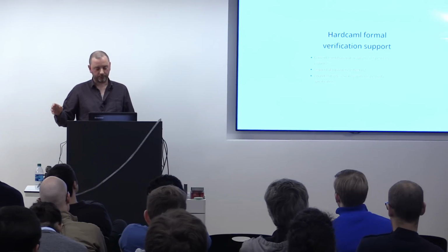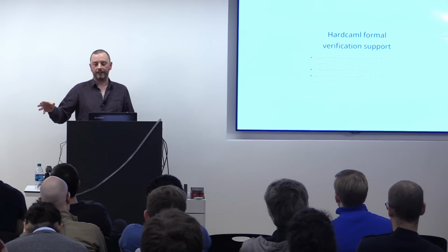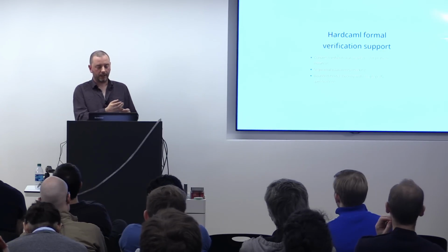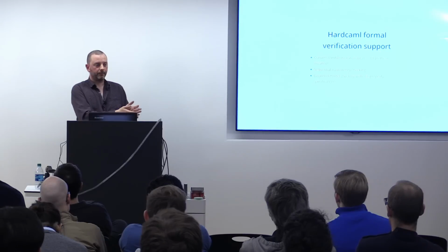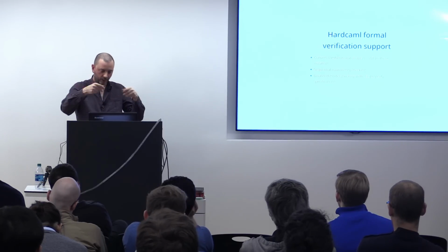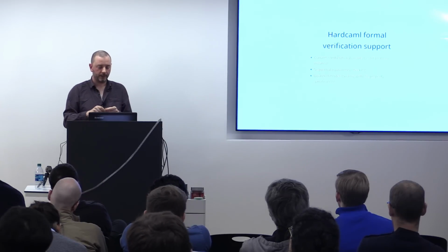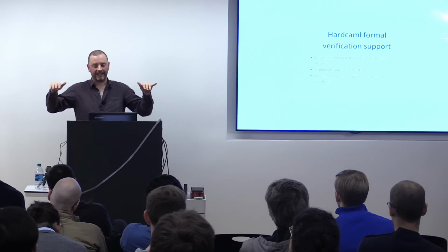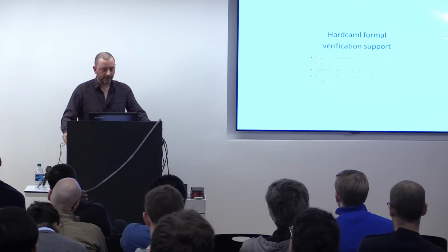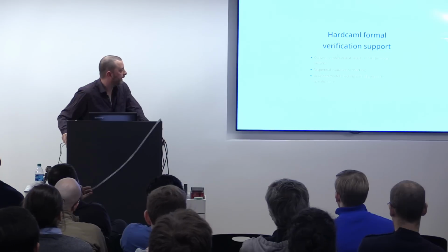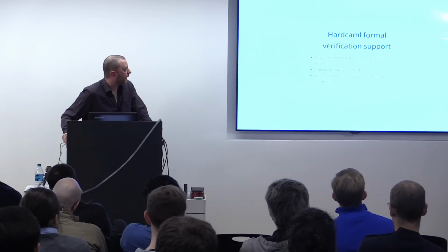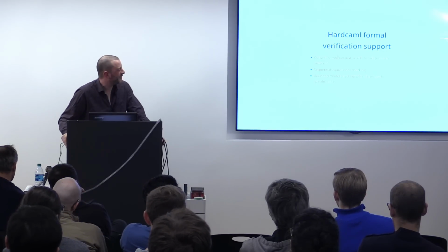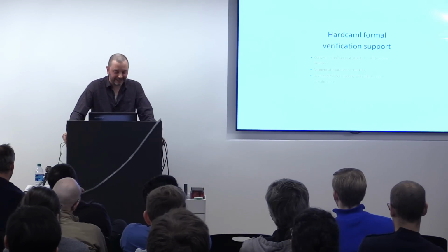Well, I used this open source tool called Yosys, which converted the Verilog into this low-level netlist, which I could then load into HardCaml and then form a SAT problem comparing the outputs, asking, are all the outputs always equal to each other? The trick here is that both circuits have to have registers in exactly the same places. To lift that restriction, we have bounded model checking. So I've got a bounded model checker. I don't necessarily trust it yet, but it kind of works on small cases.